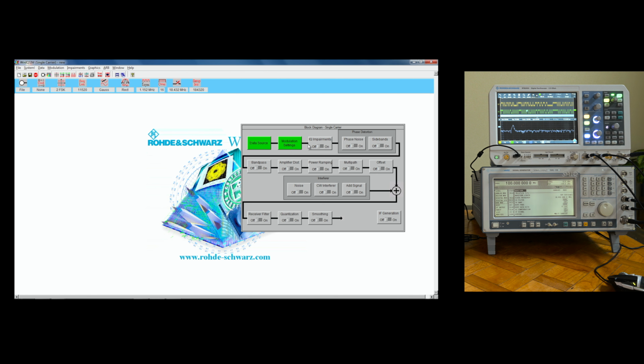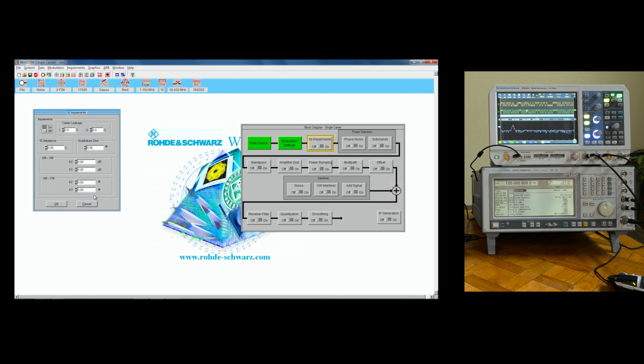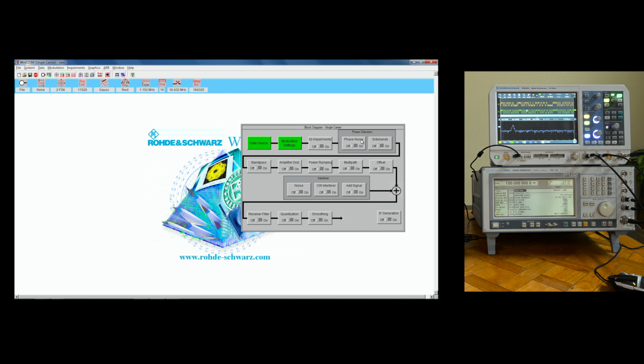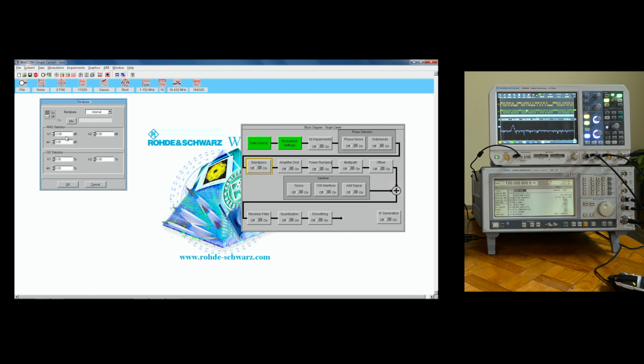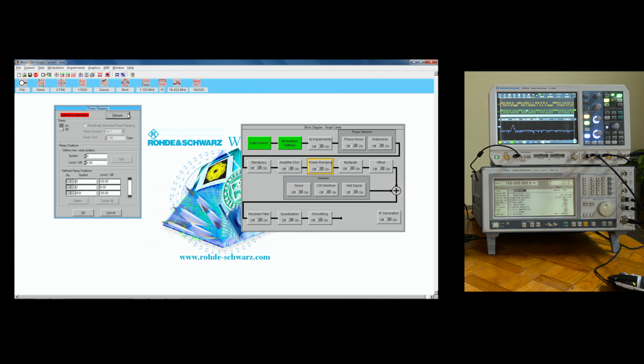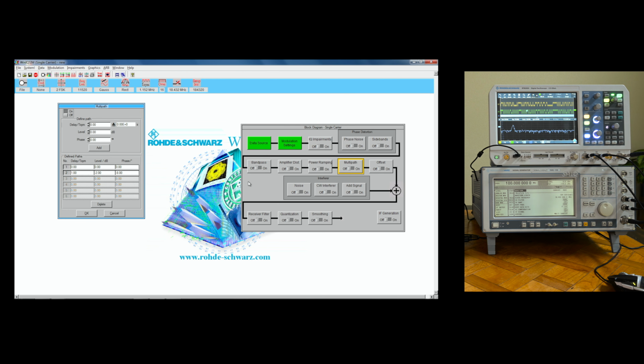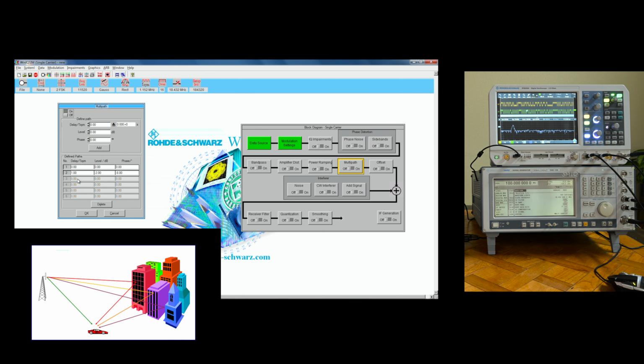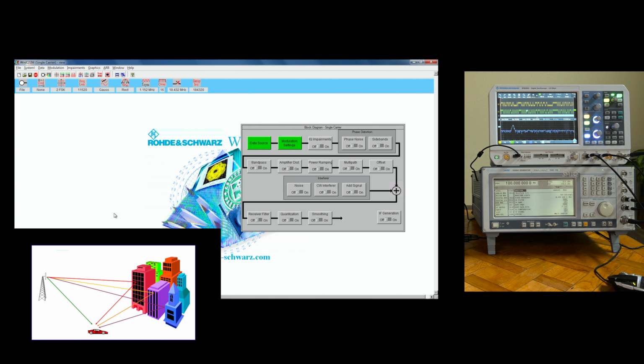Now we only looked at the modulation setting. We have the IQ impairments, in which we can make deliberate errors into the IQ signals. We can distort the phase of the signal that we're working with. We can add bandpass filters here, and turn them on and off. We can have amplifier distortion effects. We can have power ramping. We have multipath effects here, so we can define several reflection paths where a signal comes in as a delayed and possibly weaker version back into the signal.